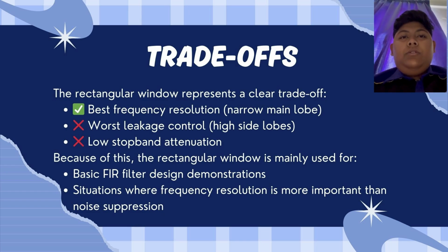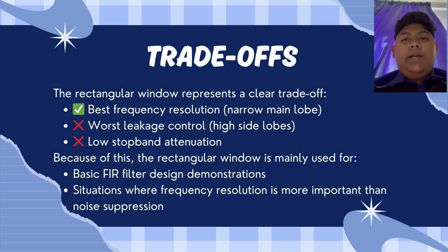Trade-off. The rectangular window represents a clear trade-off. Best frequency resolution, narrow main lobe, but worse leakage control, high side lobes, low stop-band attenuation. Because of this, the rectangular window is mainly used for basic FIR filter design demonstration, or situations where frequency resolution is more important than noise suppression.